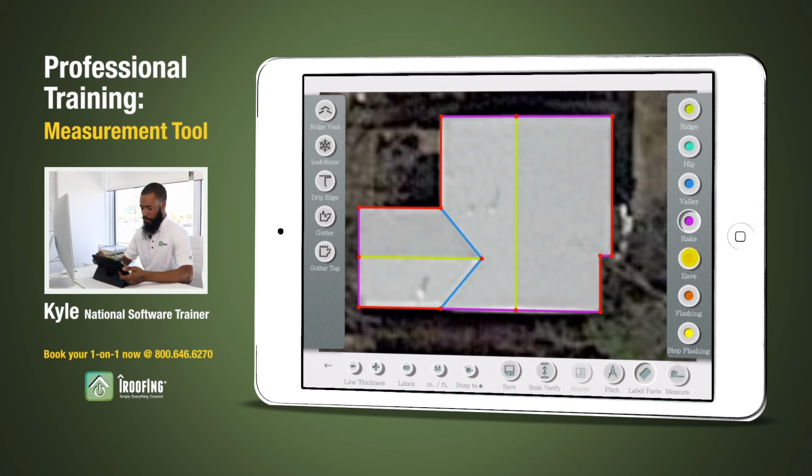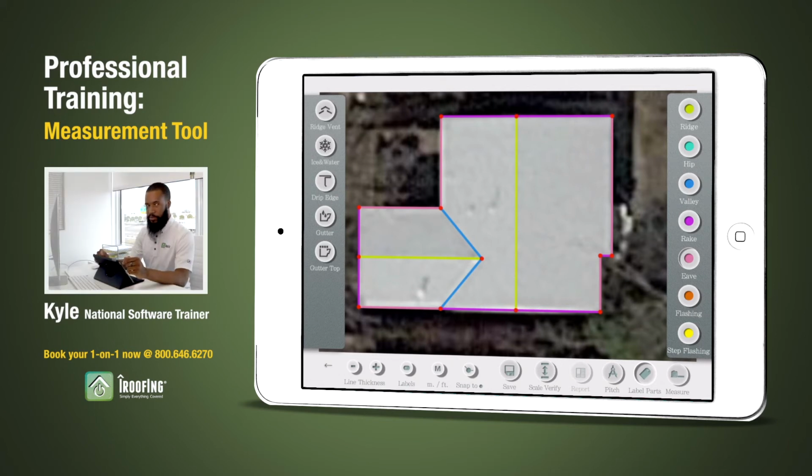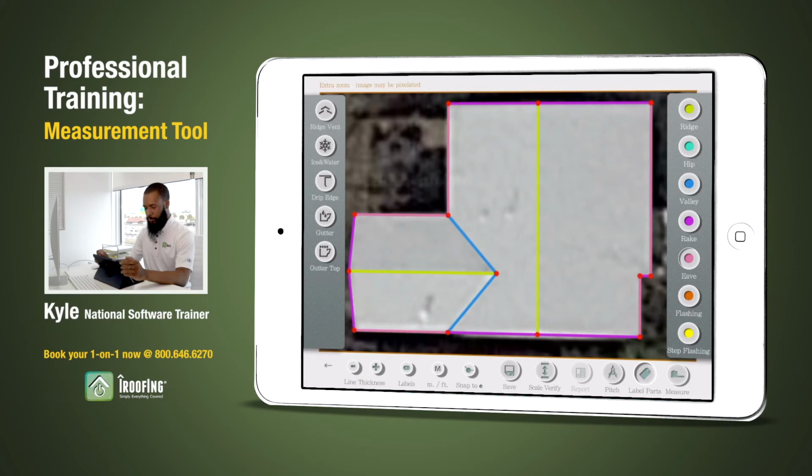Now I need to tap on the color for eave, and do the same thing for all of my eaves. And your goal when you're labeling is to make sure that you don't have any red lines left over. So if you have a red line anywhere on your screen, you have not completed the section yet. Now from here, the last thing we need to do is to set the pitch for the roof.